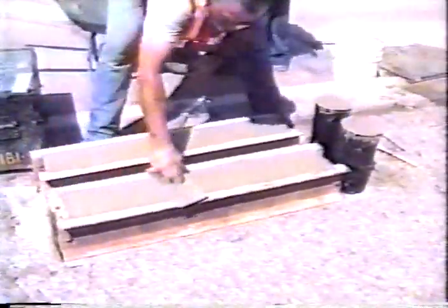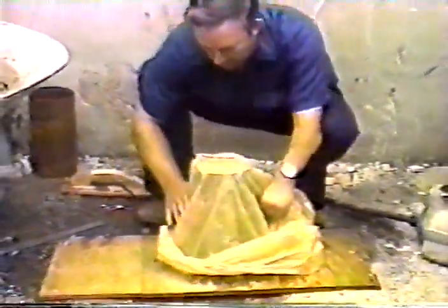Normally, a wood or magnesium float is used to finish the surface, but a steel trowel is used if specified. Immediately after they're finished, the mold should be covered to prevent evaporation. Polyethylene sheeting is usually used for this purpose. Alternatively, wet burlap may be used, covered by plastic.